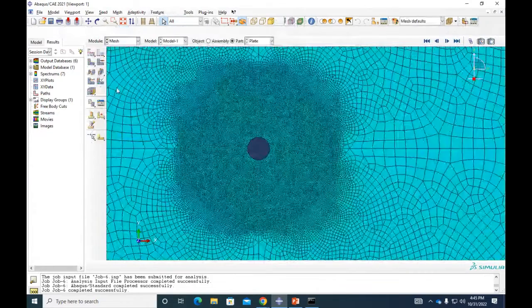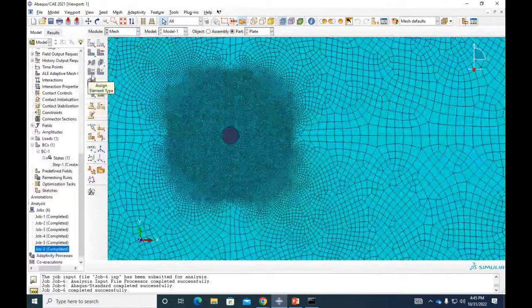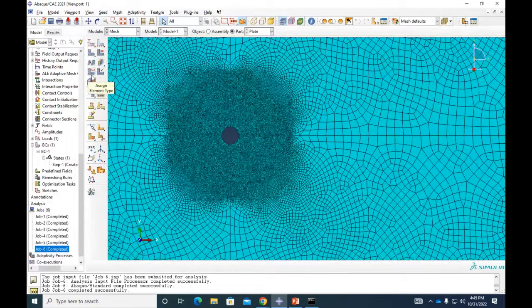refined. For your project, don't worry, you don't have to do all of these meshes. Just a sufficiently good mesh. What is a sufficiently good mesh? Just try to do some research. Like if you see beams online, what element type or element size they use. If you're doing shape optimization, or some analysis of a 2D plate or something like that, then try to look at what people usually use online, all right?